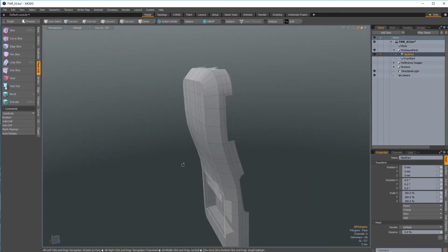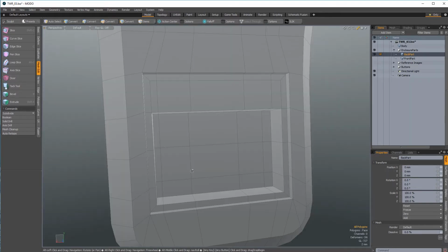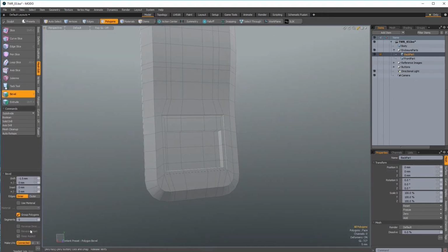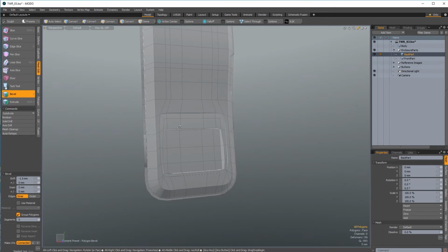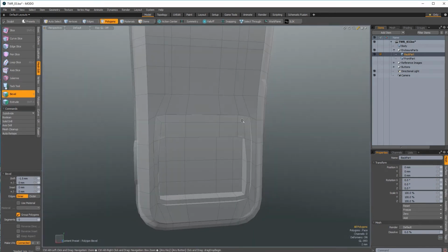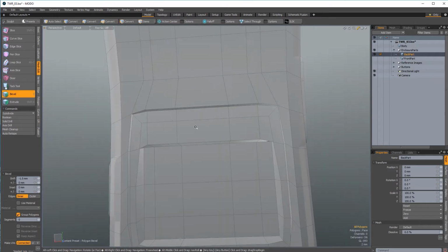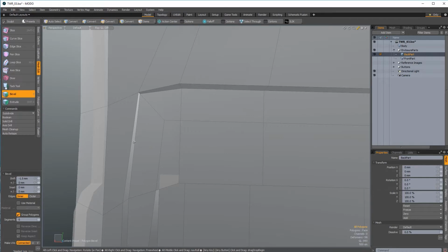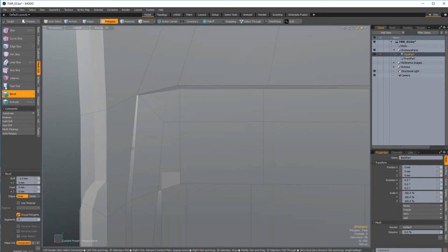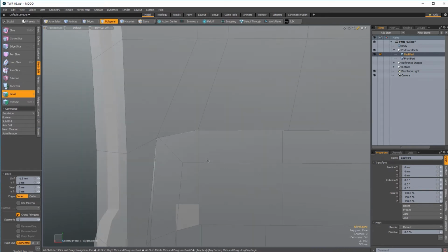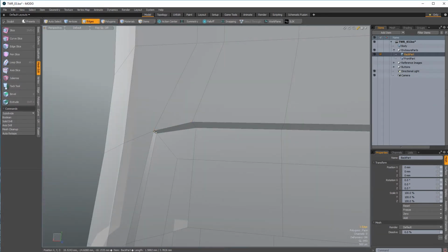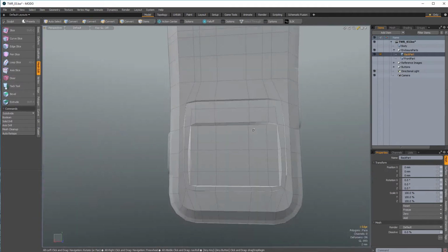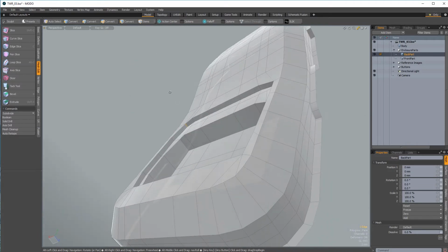And the thing that's going to make this difficult is our battery hatch. It's going to mess up our bevel thicken, and I'll show you what it'll do if we try. So let's just apply the same bevel, and you can see that it's now sort of drooped in the edges, and that's because the bevel operation is trying to extrude each surface along the normal. So this one's trying to go this way and this one's trying to go this way, and then this edge just kind of gets pulled between the middle. It just sort of picks this average position between the two of them, and then you get these sort of droopy corners, which we definitely do not want.